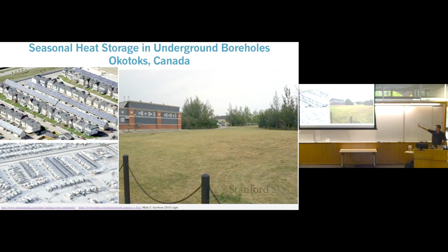And then in the... well, all year the heat is recycled, but there's also a boiler inside that building that most of the heat is coming from. But during the winter, when the snow is on the ground, then you need to take out some of this heat. And so you send cold water down, heat gets transferred to the cold water, and then the hot water gets piped to the buildings. And this heating system supplies 100% of the year-round heating for these 52 homes.